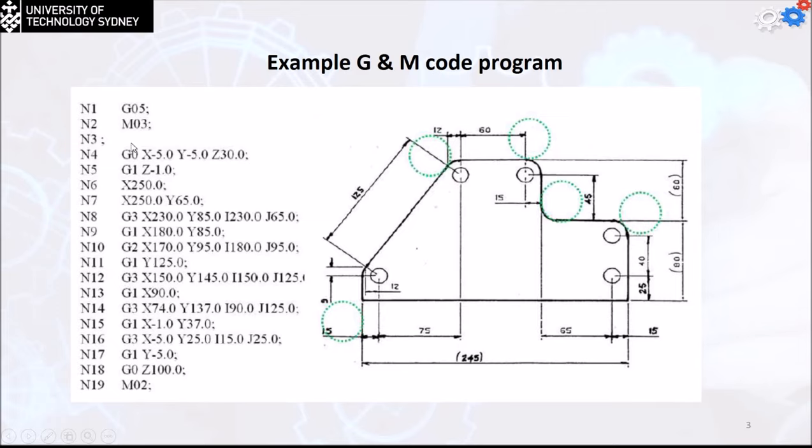We're going to explain the meaning of this, but if you make a comparison between what we have in the code and what we have in the diagram, you'll get a full idea of what's going on. First, we have the first position. If I'm going to move clockwise, we have to move to the second position, and so on. And we're going to change between what we call linear interpolation and circular interpolation.